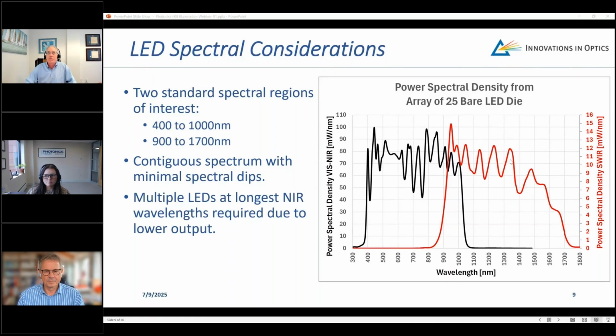So with systems that are air cooled, you would have to elevate the temperature well above whatever the room's going to be, and then you could control the fan speed to control the temperature. The downside of that is that by elevating the temperature, you're reducing lifetime and output of the intensity.